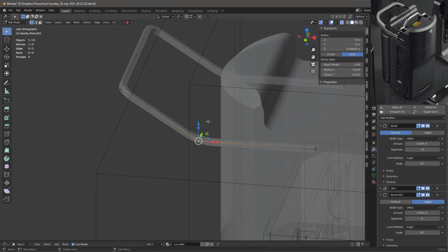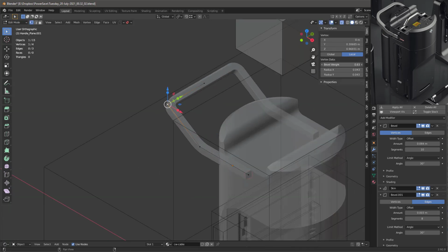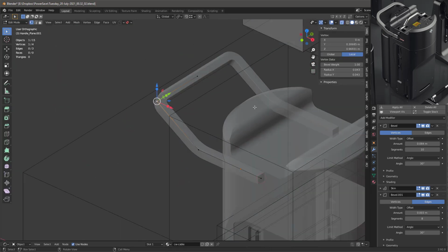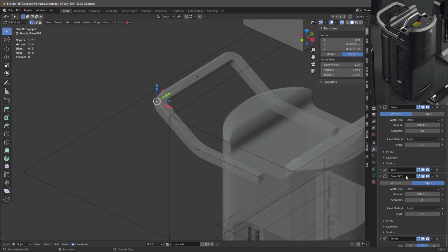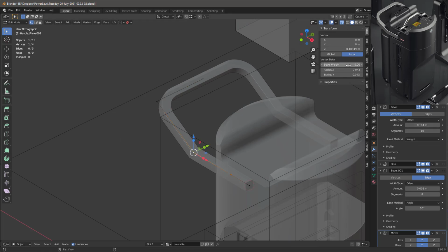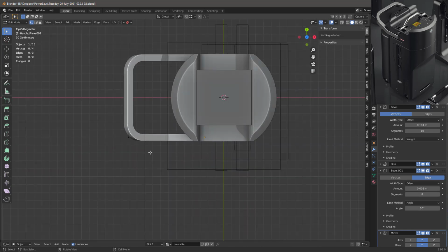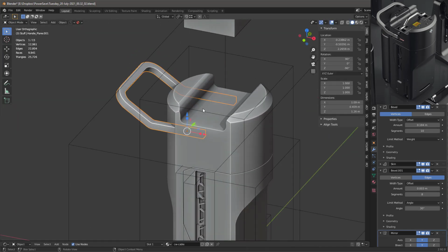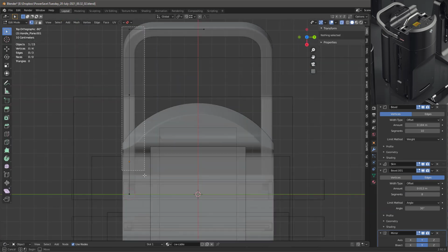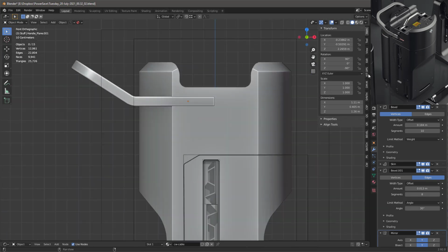So what I've done is I've applied the scale, and then I've gone ahead and selected all the vertices and hit the Alt S key to scale that up, because that's part of the skin modifier that's being used here. And once I've got that done, then I can go into the vertices and add more bevels, as well as a heavier bevel weight for those. And now I'm also adding a little more weight around the sides, and you can see I'm moving it in and out and adjusting it so I get it pretty much the way I want it.